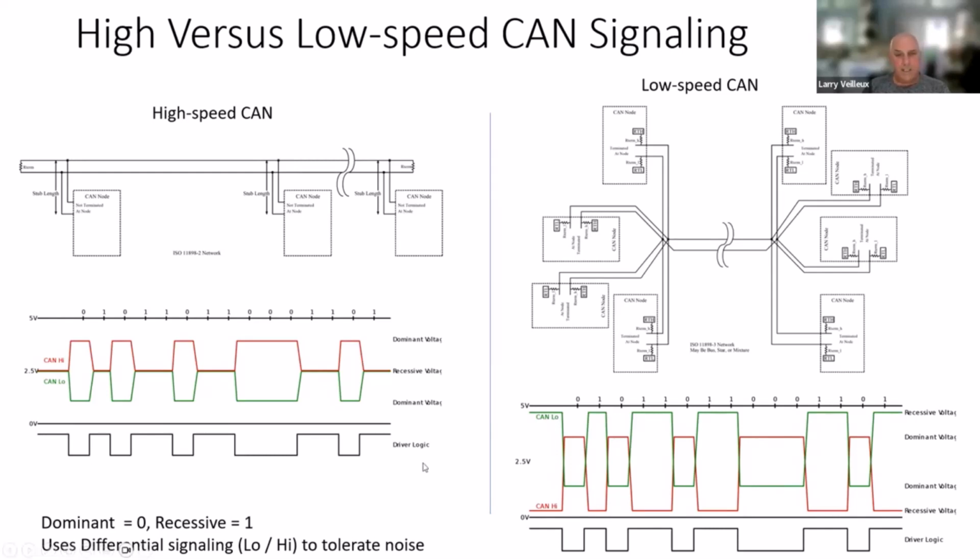more robust. So try to keep in your minds and remember, the dominant state is the higher voltage and it represents a 0. The recessive state is the medium voltage and it represents a 1. And by the way, you might be wondering, when there's nothing there, why don't I just have no voltage on the wire? Because if the wire gets broken somewhere, that will cause no voltage in a certain part. And if no voltage is your medium level, how do you know that something went wrong? And so it helps with that aspect of things as well.